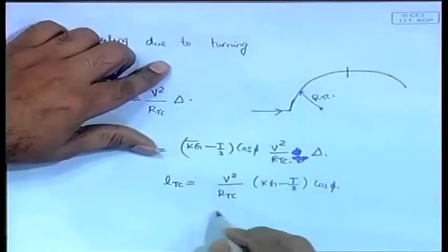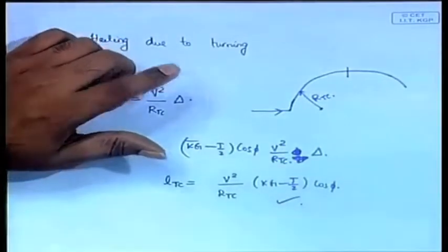KG is for the whole ship, in fact, and most of the weight of the ship is up in the top region, because that's where you are putting the cargo and all that. So in general, in 95% of the cases, KG will be greater than T/2. I don't know if there are cases where KG can become less than T/2. Some particular type of small boat, probably very small boats, maybe it can happen. But in general, it's like this. So this is that important point.